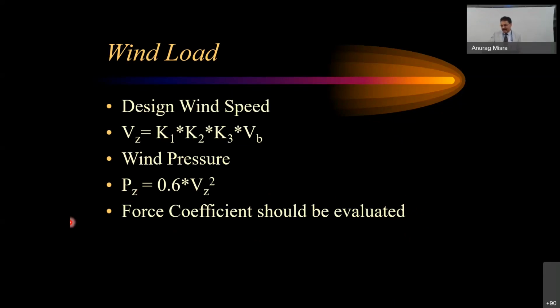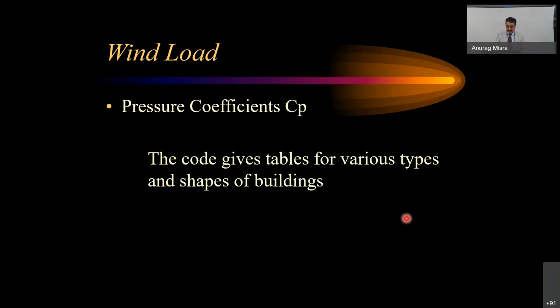properly. I am sure that you must be considering that internal pressure coefficient and external and the net one need to be taken into design, depending on what is the opening provided in these structures. So this part has to be taken very carefully, and then the net pressure which is going to be exerted either upward or downward has to be taken for the design of various components.